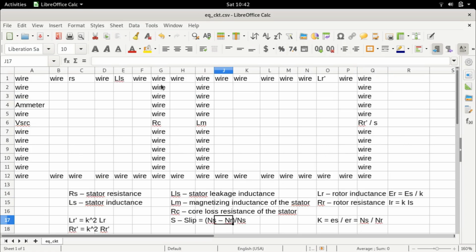So the way we are going to go about it is, as always, we are going to connect this single phase supply to an induction motor which will be modeled as a voltage source in series with a resistance, thereby forming some form of a current source. Because what we're going to do is take this voltage source, apply it to the induction motor, and according to the voltage source and the state of the machine, which means depending on the speed, this motor will draw a certain current.